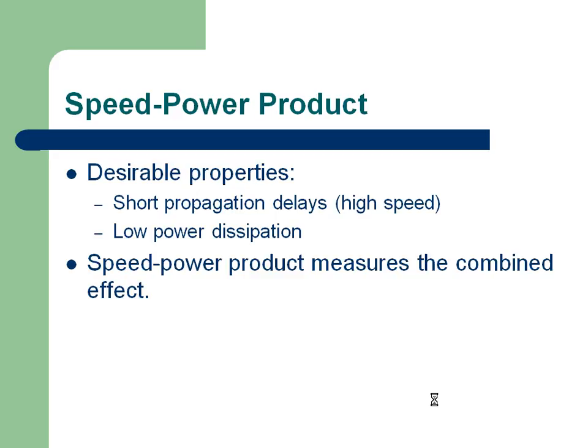So it is something like this. When you are trying to compare TTL, CMOS, ECL and all, just simply saying CMOS fan out is more may not be a good characteristic method. Why? Because CMOS fan out is more, but each gate takes a long time to switch. So usually what we do, we take a product of the power that you are burning and the delay. Speed power product, that is what you need to achieve.